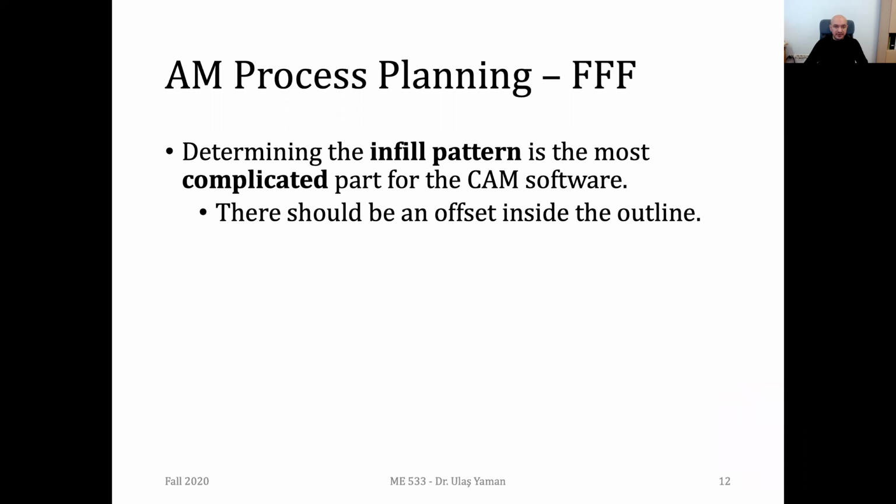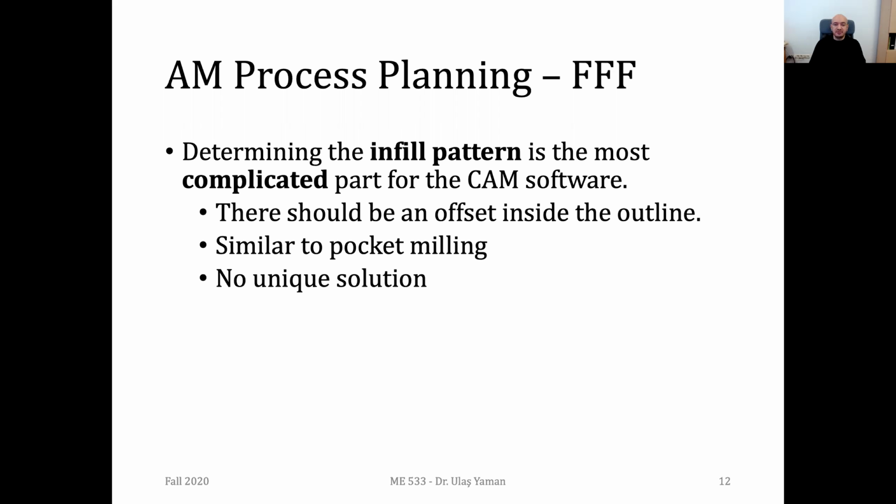So in the CAM software, as I mentioned, we can define different infill patterns, even complicated ones. And at the outer side of the slice, you need to have a kind of a shell. It's very similar to a pocket milling operation. If you are aware of CNC milling, you start with the profile and then go inside that pocket and continue removing material.